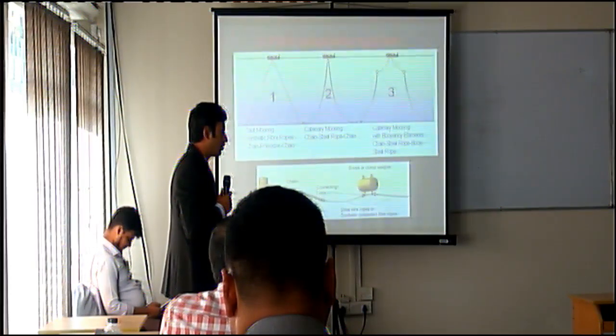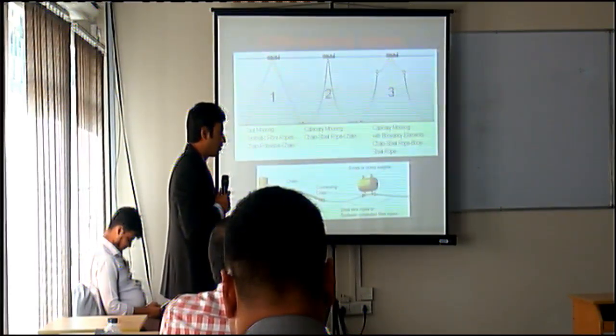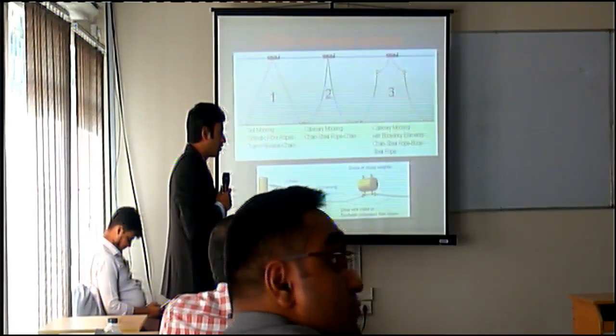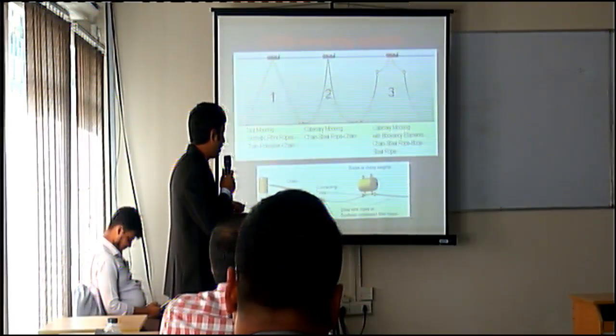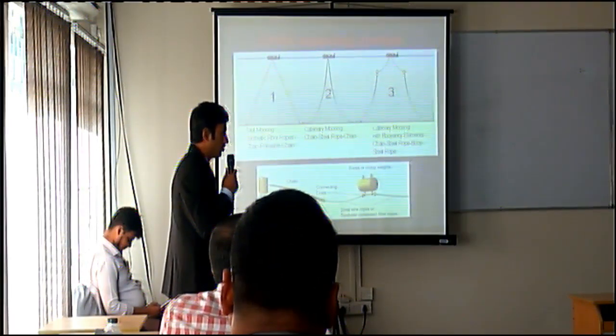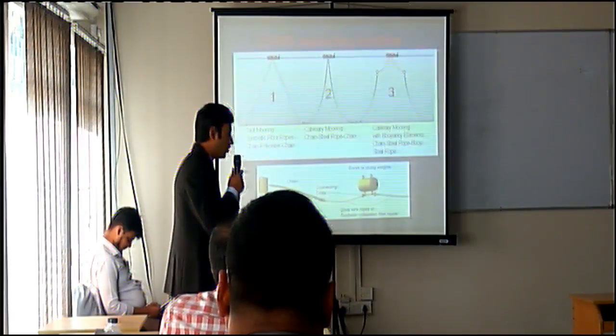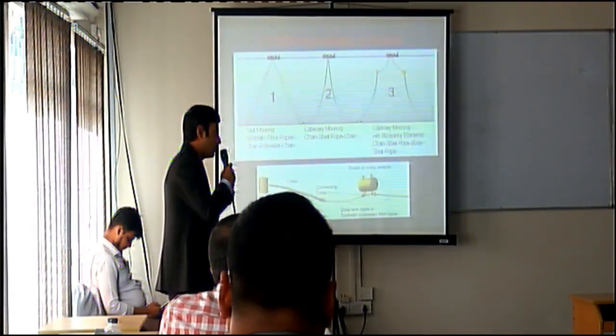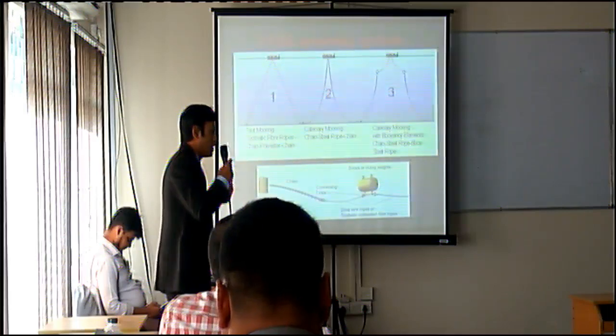Once I apply tensile load and then compressive, for this type of loading, is your method valid? For the mooring line we only account for the tension load, in one direction only, because the vessel's mooring line only gets tension. It doesn't get any compression.